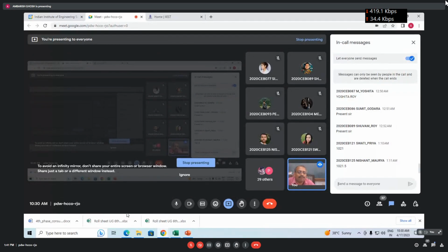Pi d square by 4, individual pile, into cohesion. Tip cohesion 40 will be there, and 9 you use. Then you add skin friction and point bearing together and divide by 2.5. You will get the pile capacity.